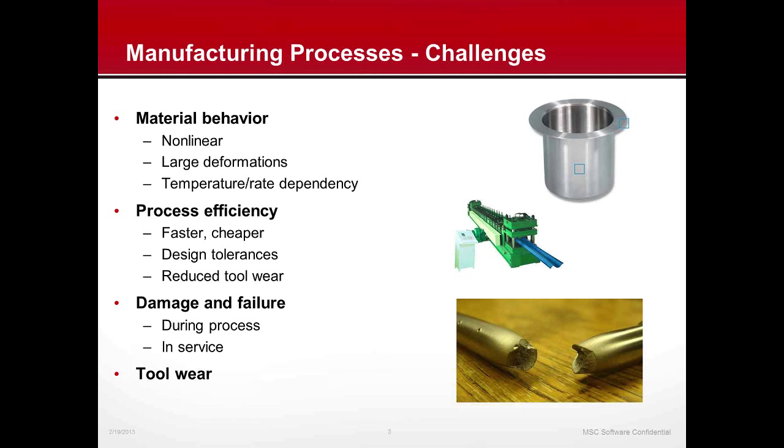There are various challenges involved in deciding on the process that is used to make a part, and to start with, one needs to understand the nonlinear behavior of the material that is being formed or worked on. And at higher temperatures, the time and temperature dependent responses become much more prominent, and they play a role in residual stresses in the final part.